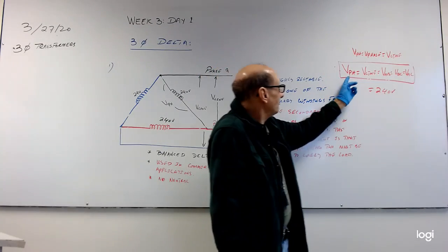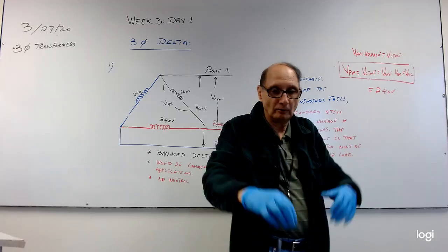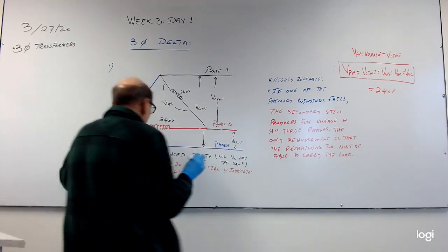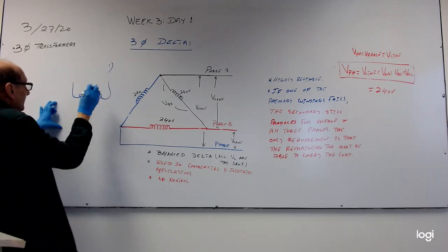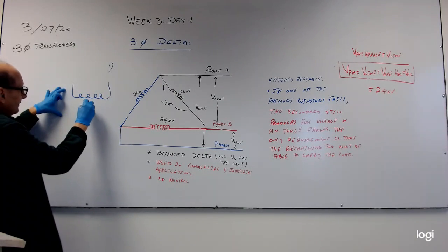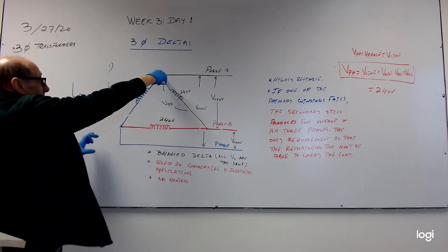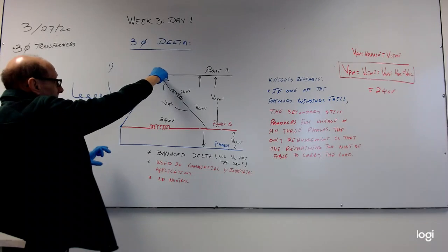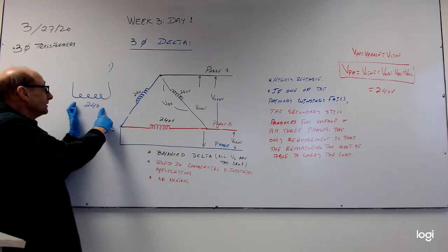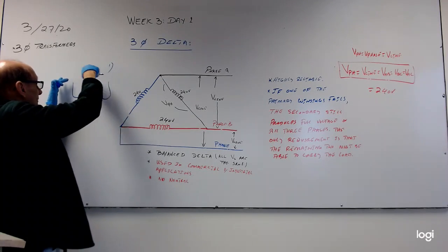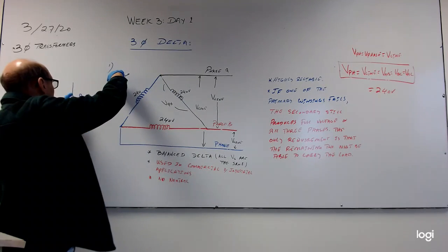So the phase voltage, which is across an individual winding, I can drag up here. This is your phase. If this is 240 volts, they're all connected together. These 2 points are connected right here, and right here, and right here. So you get 240 across here, the same voltage, 240 between these 2 points, because you have a point up here and a point down here.